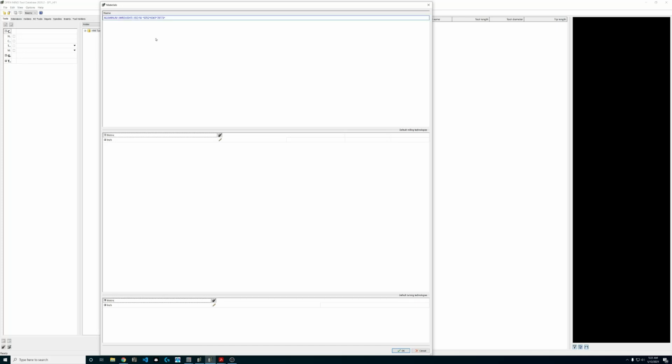Something else I like to do, I like to add numbers, and that's because you'll see this trend follows in other categories as well. hyperMILL likes to do some weird stuff. Sometimes the menus are alphabetical, sometimes they follow some sort of number sequence, and sometimes they just are in whatever order you created them in. So it seems like almost everywhere, if you add a number, you can organize things correctly, and I like to see things organized correctly.